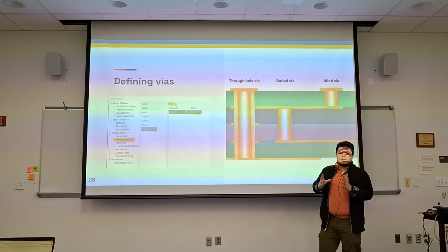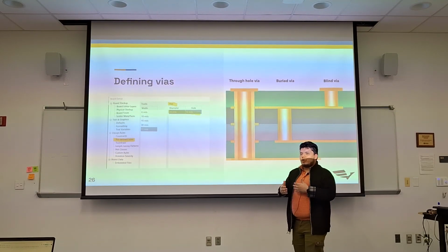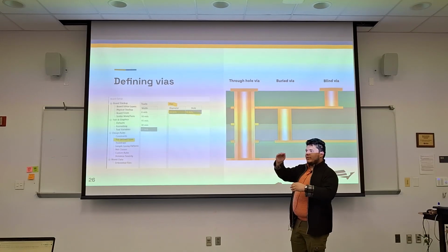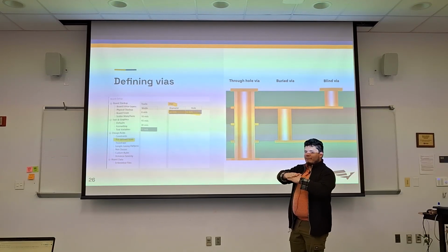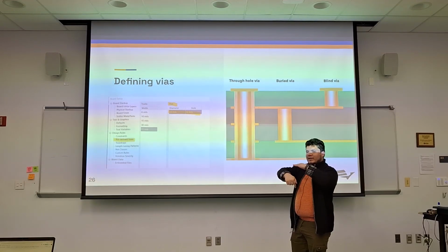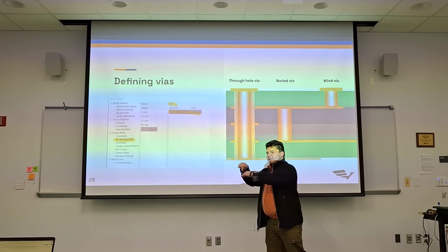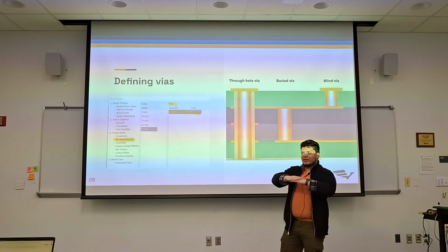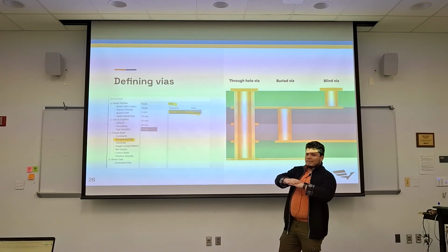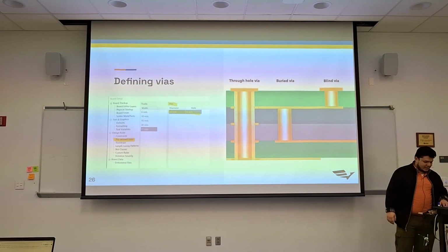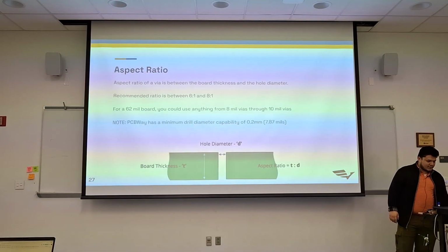I don't think you'll ever get into micro vias because those are more expensive. They add cost in processing, because basically you have to build it by layers, drill a layer, and then paste that drilled layer. So instead of having the sandwich and drilling into the sandwich, it's like drilling into the bread, the cheese, then the other bread, and then stacking them and hoping that they're aligned, right? So it's more expensive and not really needed for these use cases, but they exist.